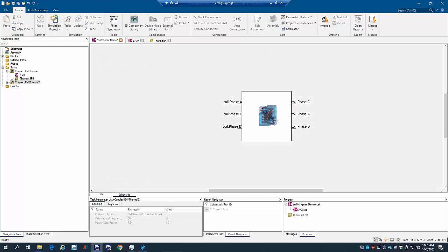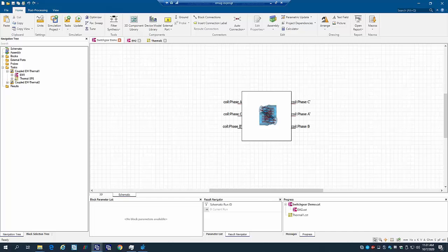Let me hit OK, just not to waste your time. Let me explain the scaling factor. Let's say you're in a high frequency simulation, usually your input power is half watt average power, 1 watt peak power. So in that case, if your actual input is not half watt or 1 watt peak power, it's actually 5 watts, for example, you need to scale it using the correct scaling factor. In the low frequency simulation, usually you enter the actual amp or actual voltage. You don't need to scale it. You can just leave it at 1, so don't get confused.